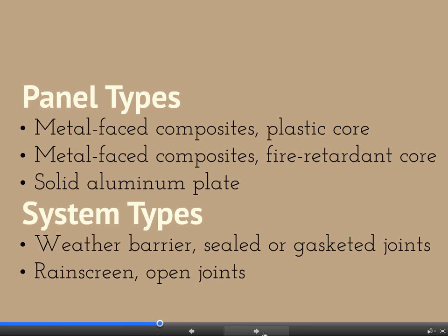Well, and I've never had an architect ask me for white. They always want black. They want the joints to disappear. So yes, there are a number of options. The colored mineral wool, for one, is certainly an option. There's another one that I saw just recently, and I don't know how many folks have even considered something like this. But foam glass, the black glass type board insulation, is now being marketed too for cavity insulation. So there's a way to get absolute black insulation, and non-combustible.